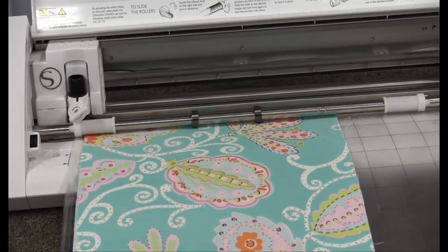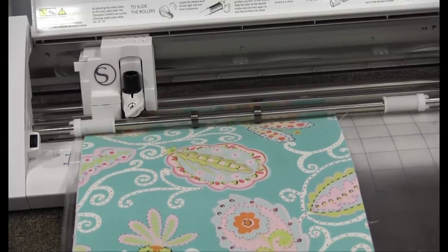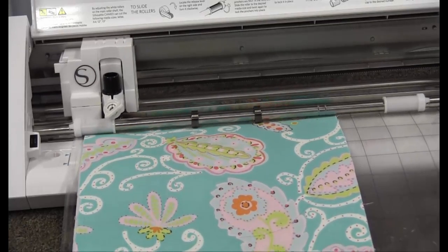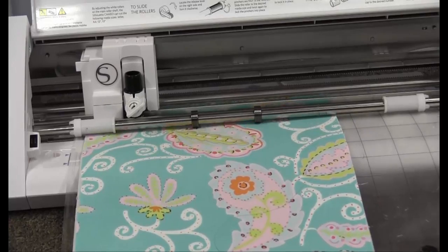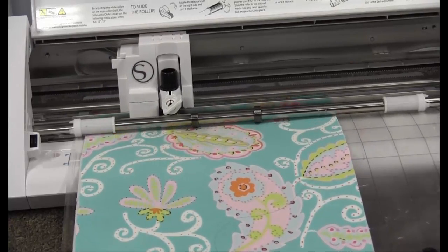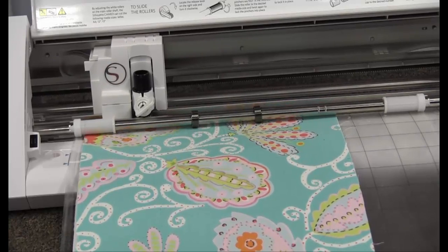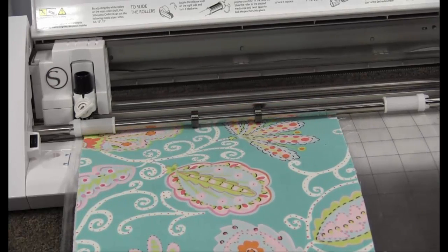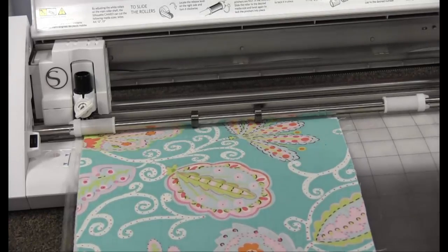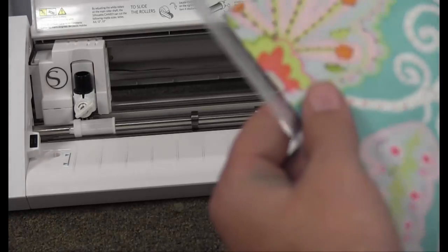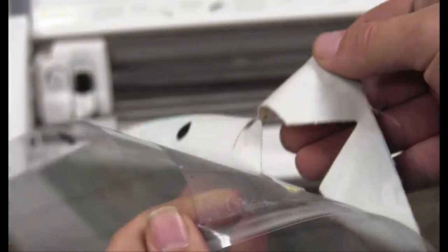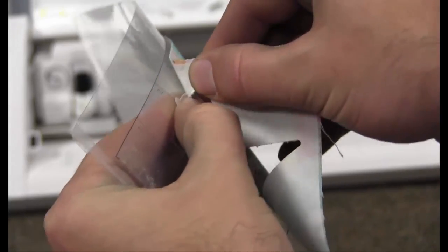Once you hit the Send to Silhouette button, it's going to immediately start cutting, and it's going to cut out your shape like you're seeing it do now on my screen. It just cuts it all out in one smooth motion, and then when it's done, it's going to stop and move the head all the way over to the left. You hit the unload button on the machine, and it'll unload it for you. And then what you want to do is go ahead and just peel away your fabric, and it should have cut out both the backing and the fabric for you.